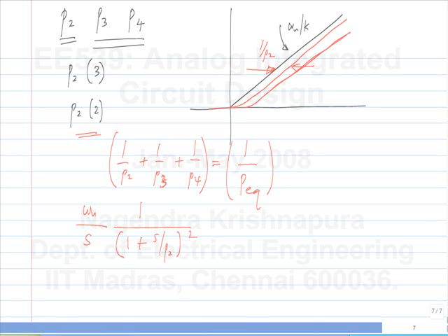So that's about the analysis of the feedback loop with non-idealities. We saw the effect of DC gain that causes inaccuracy. The effect of additional poles is that they delay the loop gain. Basically they delay the response around the loop. That's the bottom line. Because of that, it has a tendency to instability. That is, you can always have a case where you are overcorrecting on one side and then overcorrecting on the other side. That is when you have ringing. If the delay is not as large as that, you may not have ringing. But then you do the full analysis and you see that you can use this beneficially in some cases. For instance, we were able to extend the bandwidth by 40%.